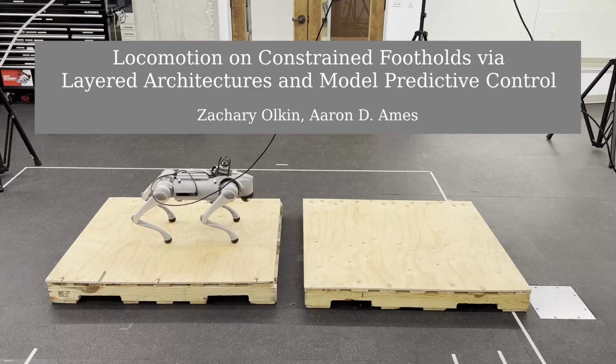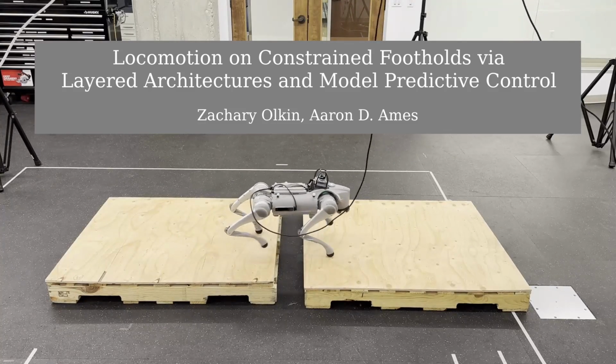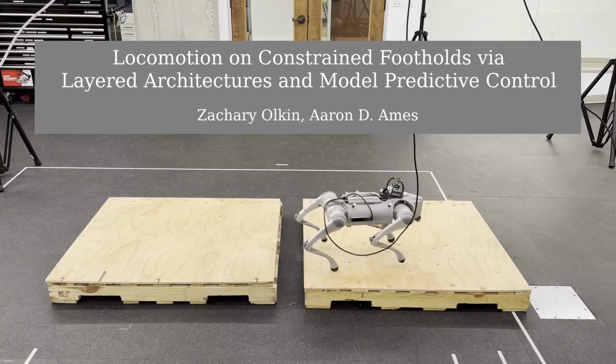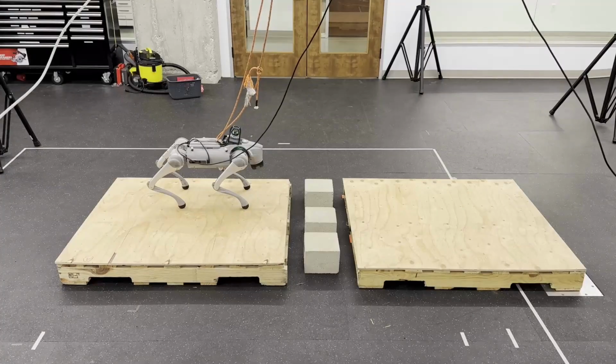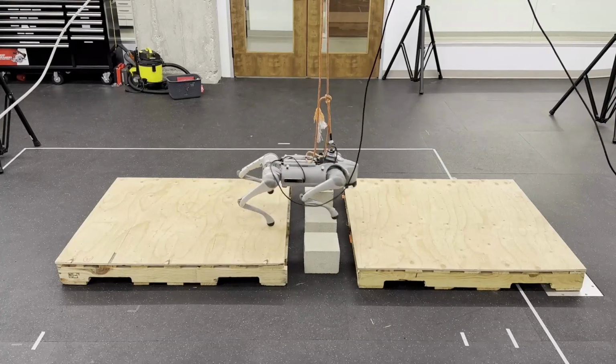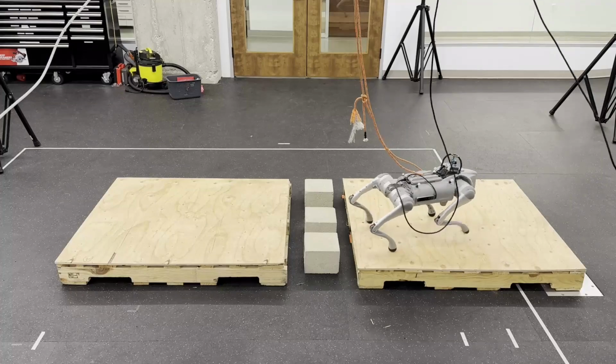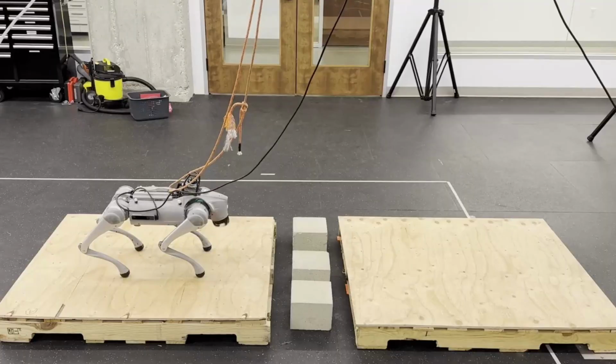We present a novel control architecture that allows legged robots to dynamically traverse complex terrain. At its core, this is a layered architecture that separates out the choice of discrete variables from a smooth optimization. Once the discrete variables relating to the hybrid nature of the system have been fixed, the resulting optimal control problem is a classical nonlinear program that can be solved efficiently with gradient-based methods.